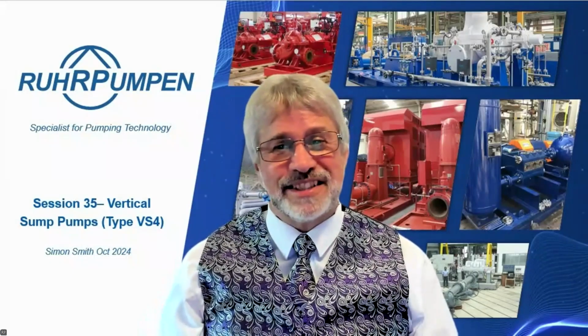Simin Moshki says, in the case of double mechanical seals, could we have one mounting plate or should we design a separate mounting plate for the mechanical seal? No, it would fit nicely in. Remember, the mechanical seal is only going in the area where the shaft passes through the mounting plate. It's going to be a relatively small mechanical seal there, and you could put a double seal there if you wish, and separately you would mount a Plan 53 pumping system to feed that double mechanical seal. Or if it's a single mechanical seal, you could take a flush from the discharge and pass it through the mechanical seal, Plan 13.